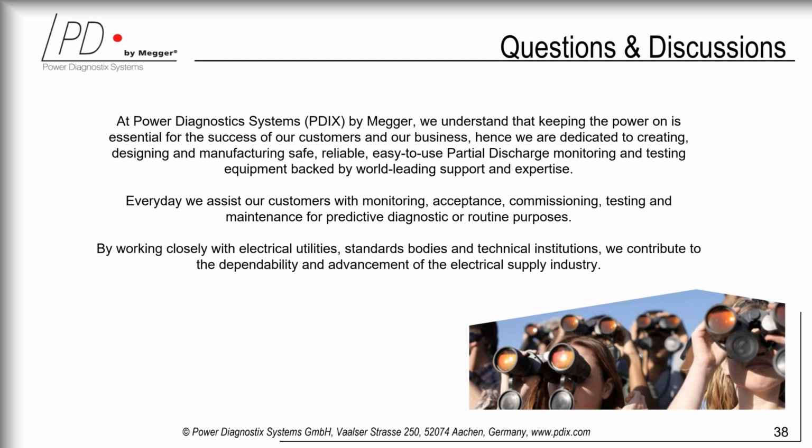If we are measuring in picocoulombs, according to the IEC 60270 calibration procedures, below 1 megahertz. If we go into a higher frequency and we measure in millivolts, then we do not have the comparison with the factory test. So here we have to set a level according to our experience, let's say, put it this way.